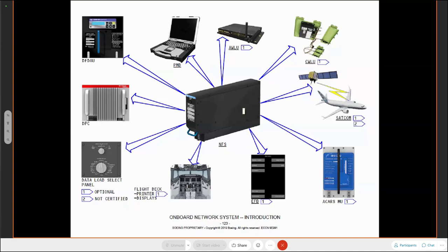It's a filing cabinet, electronic filing cabinet. At some point, maintenance will be given a job card to update the nav database. They will use a portable maintenance device or the MAX display system, and they will copy that LSAP, that new version of software, to the flight management computers. As they copy the software to the computers, it is a copy. They don't physically remove the software from the network file server. It's not a cut and paste. It's like a copy and paste.